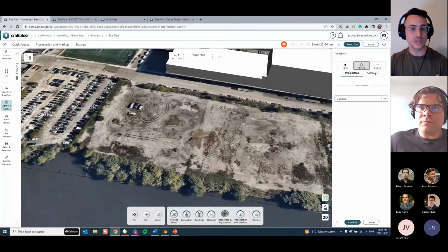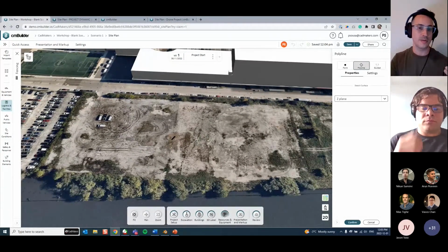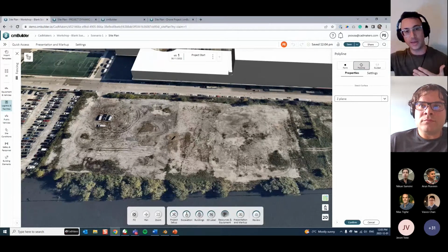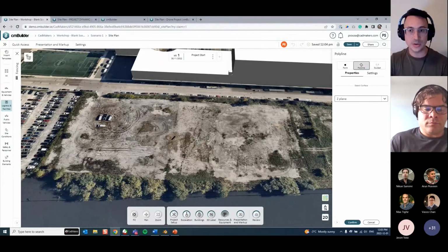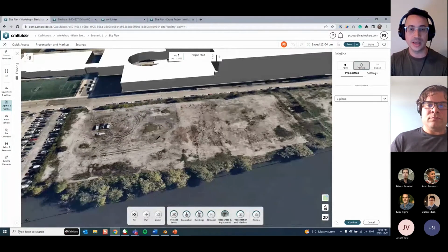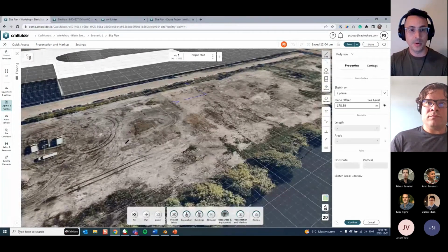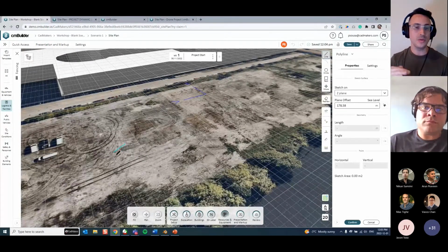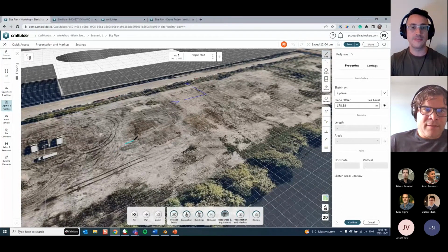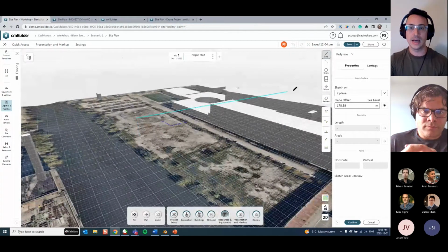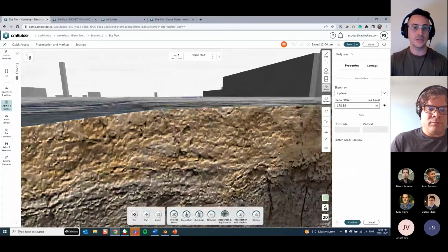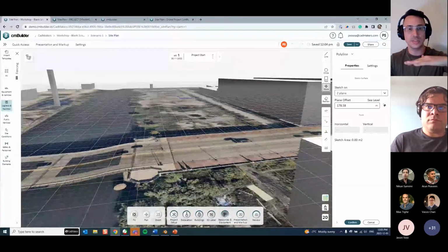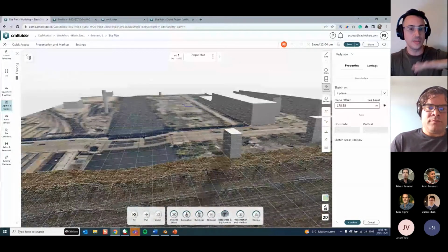The polyline for resource is going to be used as a main driver to create a pattern of placement for several of these resources in a row, right? So the moment that I start drawing, the point that I click over here will be used as my sketch elevation support, right? If I look over here from the side, let me change to move. If I'm looking over here to the side, you see that these grid lines tell me what is the position of that sketch in the 3D space.